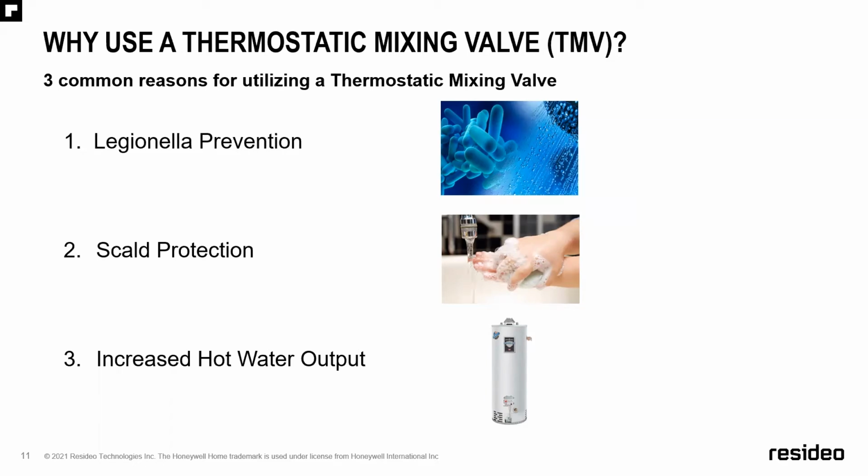Scald protection. This is a very unsafe situation when you have a water heater that you're trying to kill Legionella in, but you don't have a mixing valve. It only takes a couple of seconds to scald your skin if you're in a bathtub, taking a shower, or washing your hands, let alone a small child in the house. So a lot of municipalities and states have put in a hard requirement that you can't even install a water heater without having a point of use or point of source mixing valve to prevent that type of danger from happening.